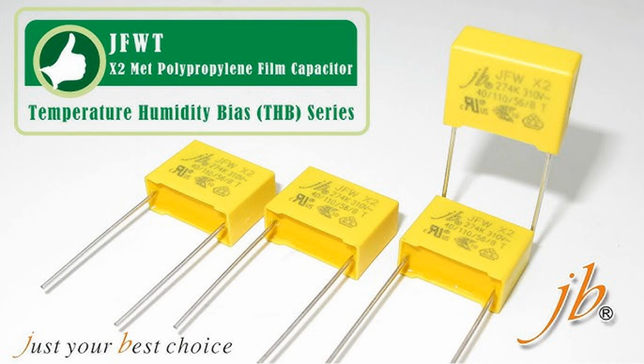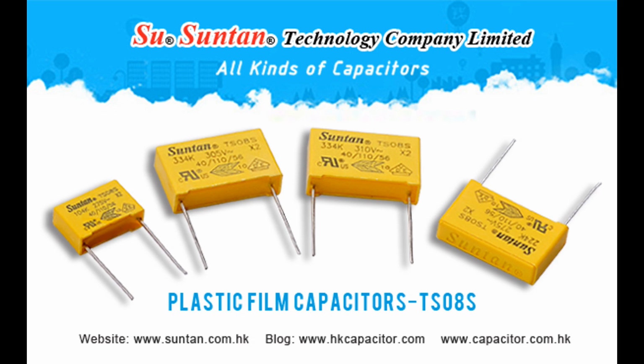Construction of a film capacitor. Film capacitors are constructed using a layered design with a dielectric material made of a plastic film and electrodes. The construction can vary slightly depending on the type of film capacitor, but the general components and structure are as follows. 1. Dielectric material. The dielectric is a thin plastic film made of materials like polypropylene (PP), polyester (PET), polystyrene, or polycarbonate. The choice of dielectric material affects the capacitor's characteristics, such as its capacitance stability, temperature resistance, and voltage